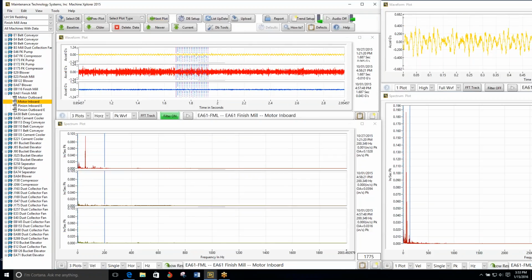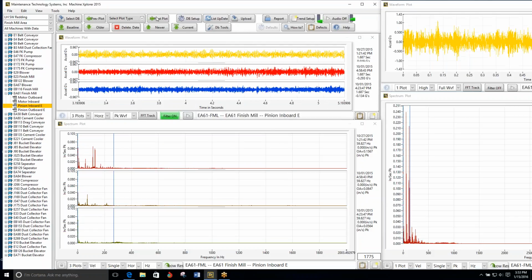And then here's the little guy. Yeah, that's kind of interesting. The peak there is at about gear mesh frequency. A little bit coming up. Oh, notice we've got a 0.24 inches per second. We can see a significant increase there. So let's go find out where that other one's coming from. Not vertical. That'll be axial. Yeah, there it is.